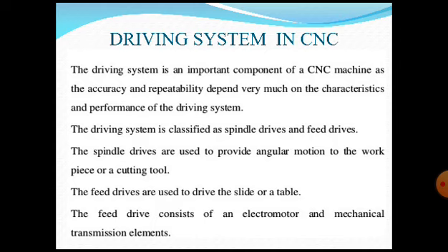The driving system is classified as spindle drives and feed drives. Basically, the driving system, that is nothing but a motor, is used for driving the spindles and for driving the table. They are named spindle drives and feed drives. The spindle drives are used for providing angular motion to the workpiece or the cutting tool. This is very, very important. Now the question comes.